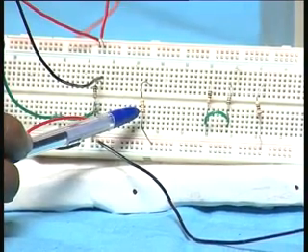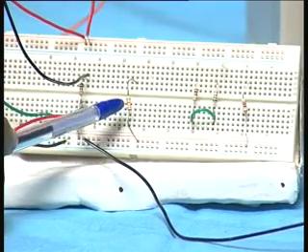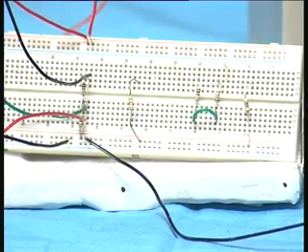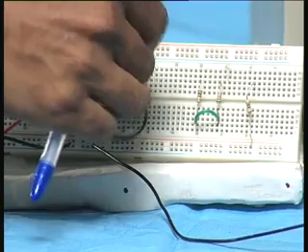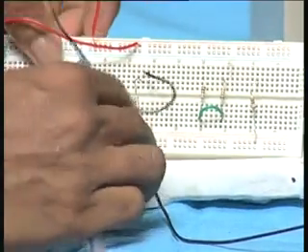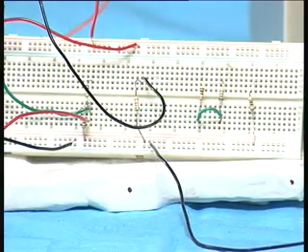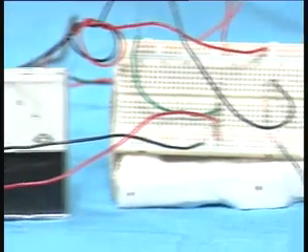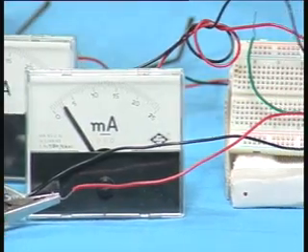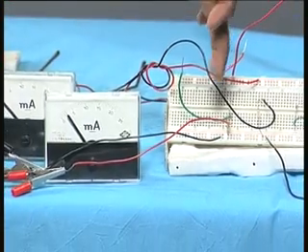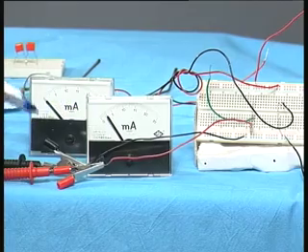It has, as you can see by the color code, three red strips, red, red, red, which is equal to 2.2 K or 2200 ohms, very close to 2000. Now, I am connecting that in the circuit, and let us see what will be the current. Now, you can see the current is the same as what you measured before, when I had two different resistors, each of 1000 ohms, now replaced by 2200 ohms, and you can see the current is almost the same as the previous case.